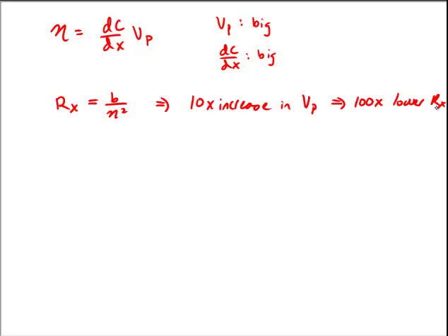And so oftentimes people reporting about electrostatic MEMS devices operate these things at 100 volts because that's the only thing they can do to get low series resistance. Every factor of 10 increase in the voltage gives you a factor of 100 reduction in the series resistance.